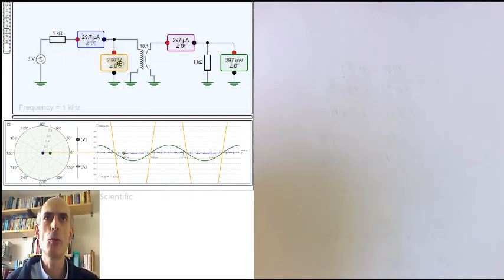The voltage has only dropped by 30 millivolts across this 1K resistor, but we've got nearly 300 millivolts across a 1K resistor at our output. We've got now 10 times the amount of output current as we are taking from our source.